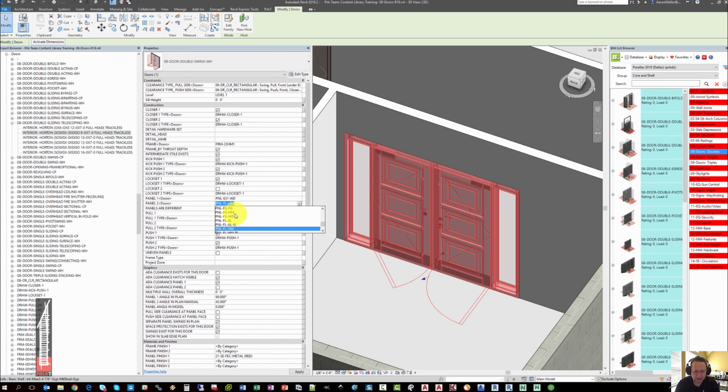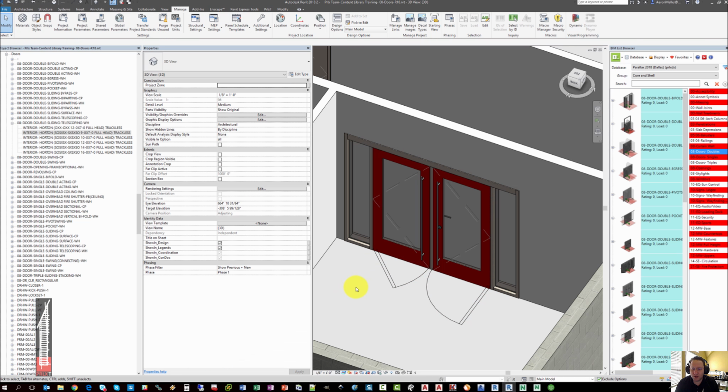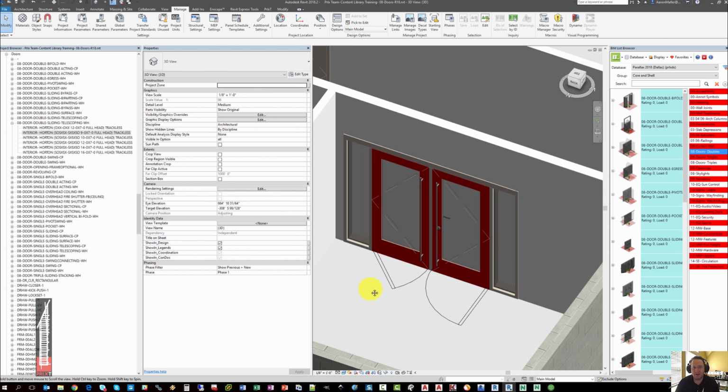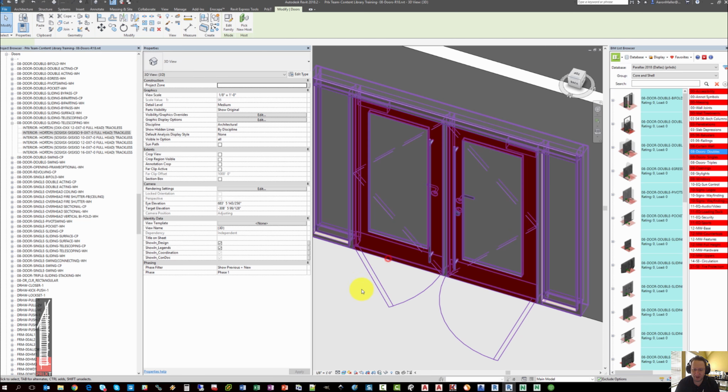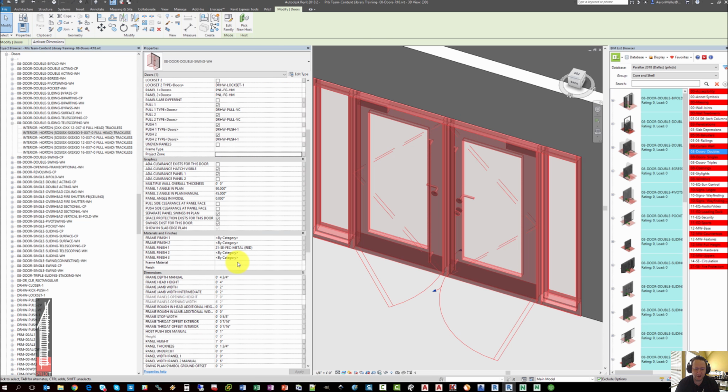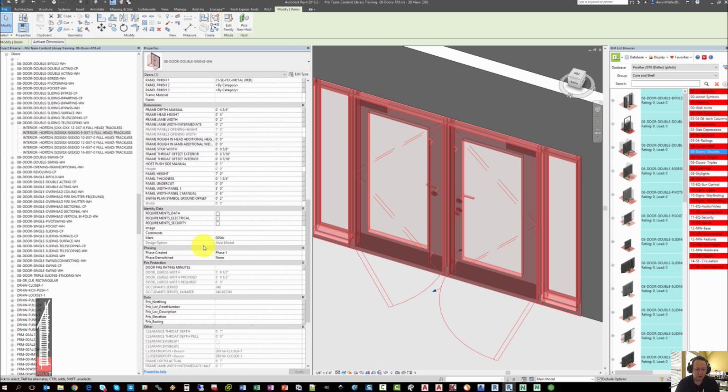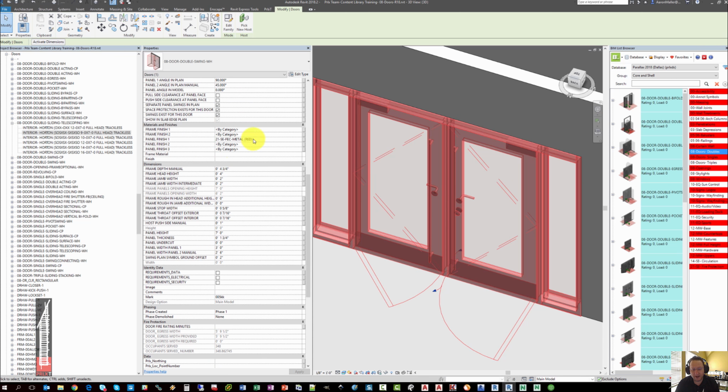More than likely, it will be things like glazed panels, where material 2 will then be the glazing. More intricate panels that have multiple materials on them may also make use of Finish 3. So in this case, you're seeing that Panel Finish 1 affects the main body of the panel, and Panel Finish 2 would be for the glazing itself. So any film or render appearance that you want to show of the glazing, you could actually change in Panel Finish 2.